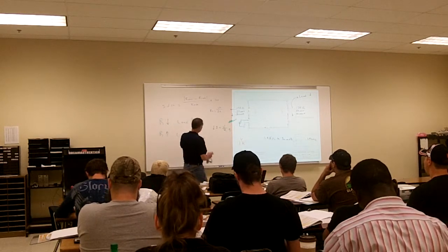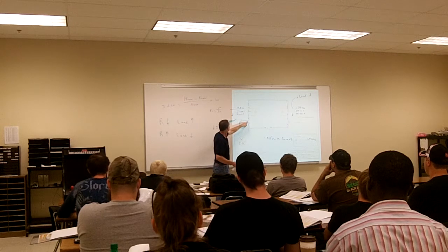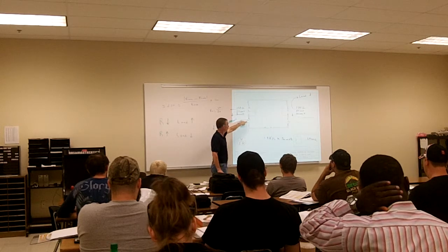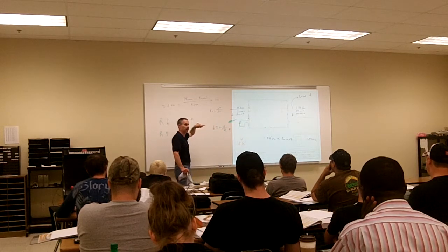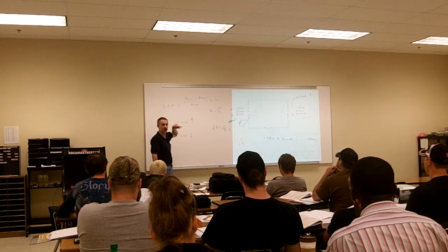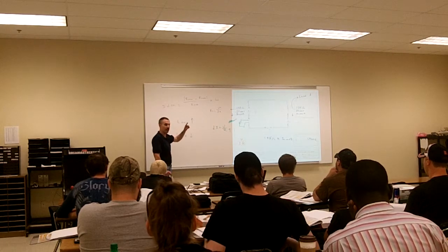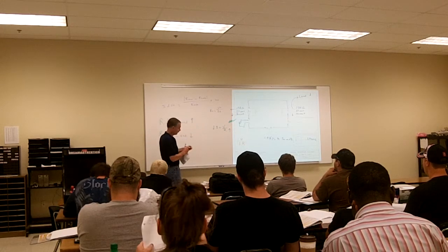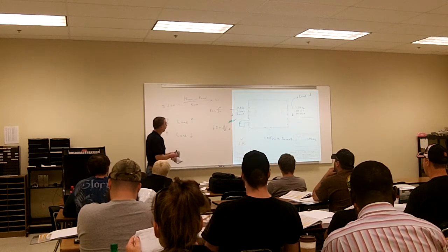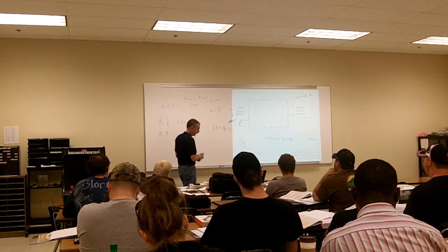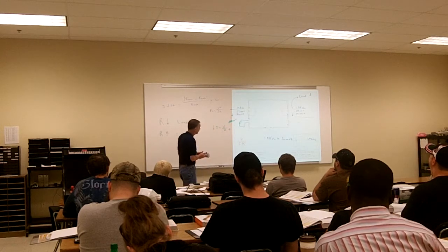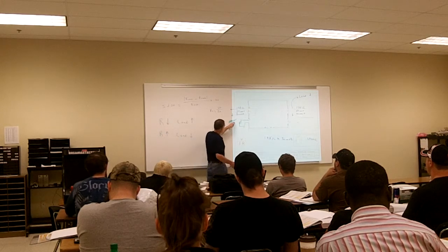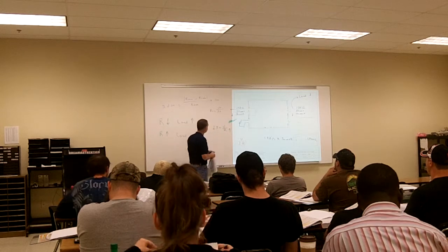Because when we measure across an open, we measure what? Your full potential voltage, my source voltage. So if that fuse is open, how much resistance does it have going across it? No, not zero. Infinite. Another thing people always get confused by is infinite and zero. Resistance is opposition to current, so if I have a lot of potential difference across it, it means I have a lot of opposition to current, meaning a very large amount of resistance. So yes, it's infinite resistance, not zero.